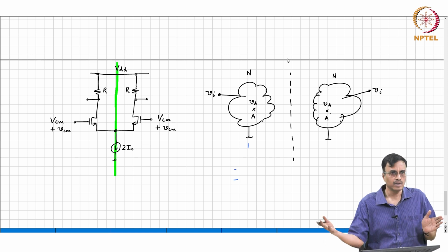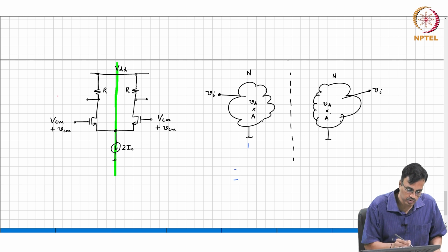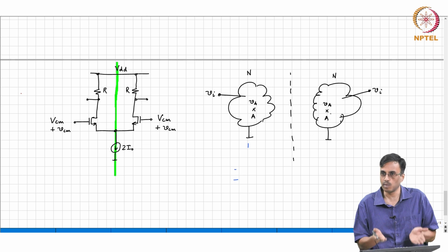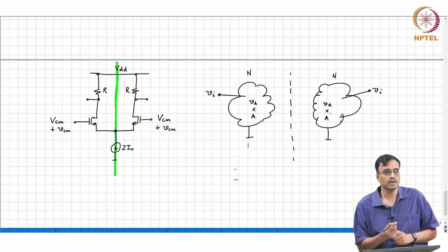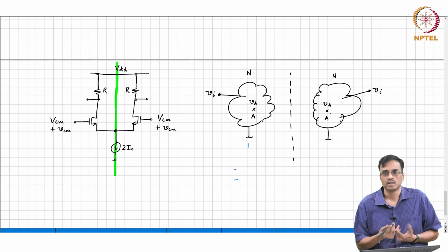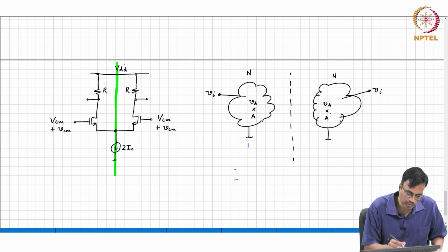On the other side, you get exactly the same. So that is now again half circuit analysis, but now it is for common mode excitation. So, that half circuit is called the common mode half circuit, correct. What should we do with VDD? Ground as usual.